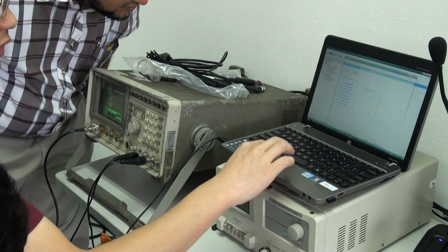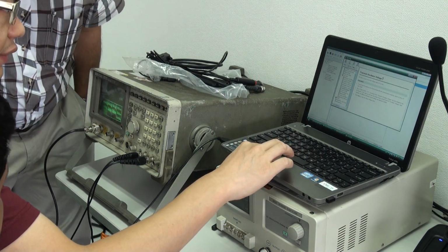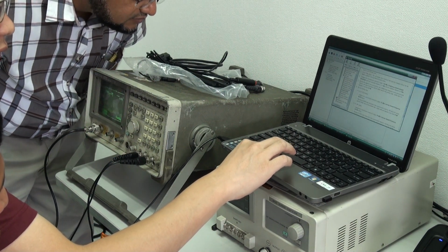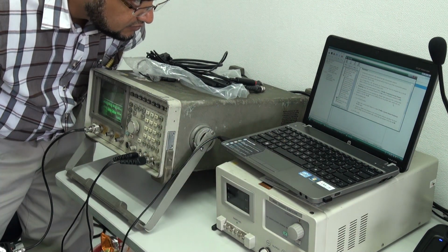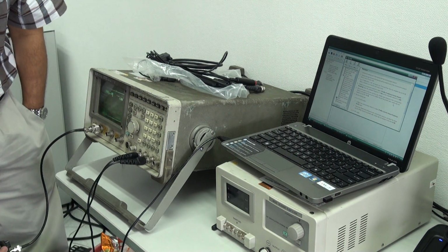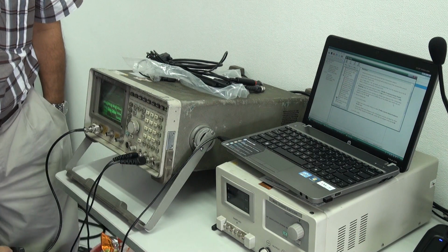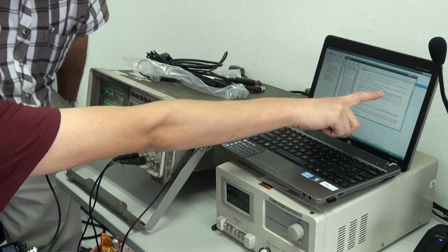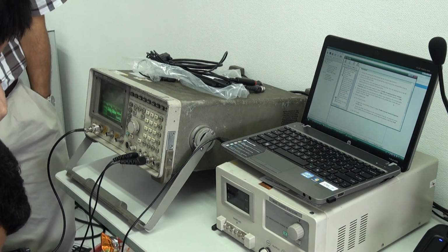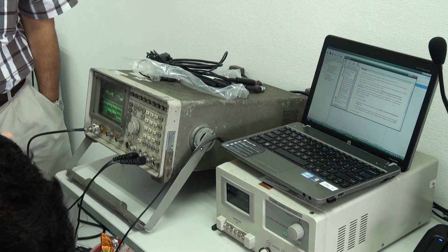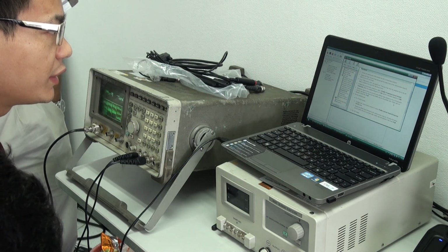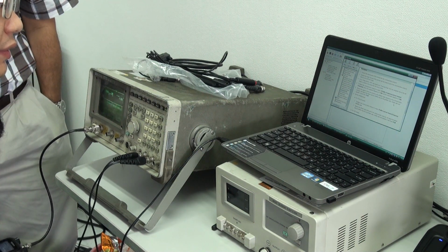So this one is for you to test, and here is the tuning step. This one is for you to test the RX sensitivity, whether the radio is good or not. Usually speaking, for DMR radios, the RX sensitivity standard is this one, minus 118, almost the same as the analog radio. Minus 118 dBm. 0.3 microvolt.